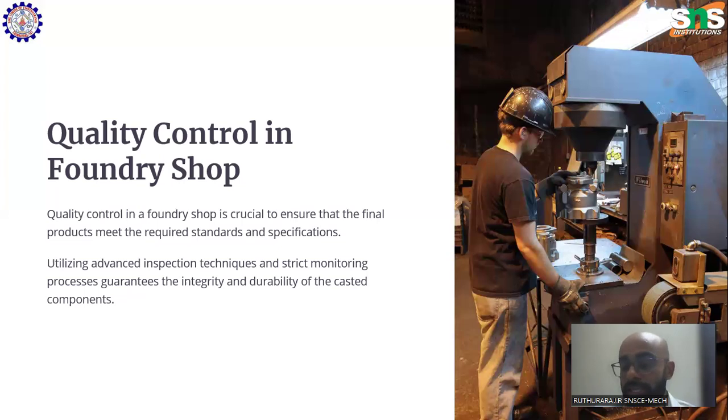Similarly, the strength can be determined. Similarly, visual inspection would be done to recognize any casting defects. And then you may go for some non-destructive testing methods to analyze its surface and the material composition. Everything is done to ensure that our finished product is of the required quality. So it can be done with the help of destructive testing or non-destructive testing processes.